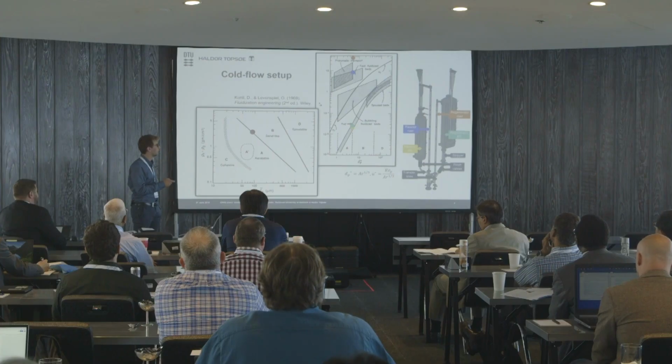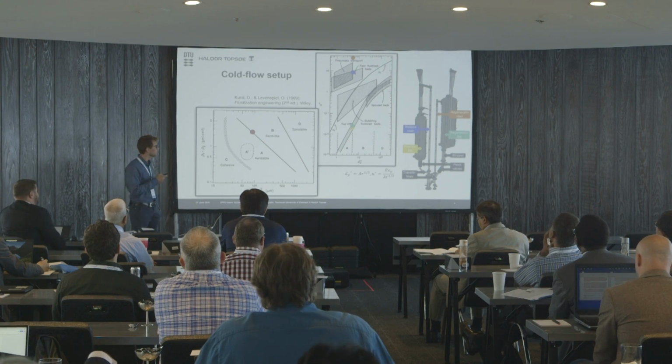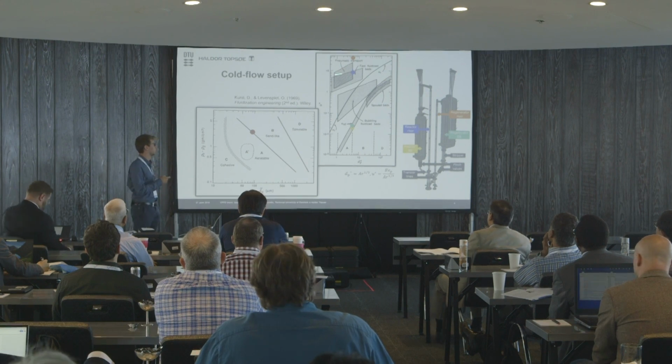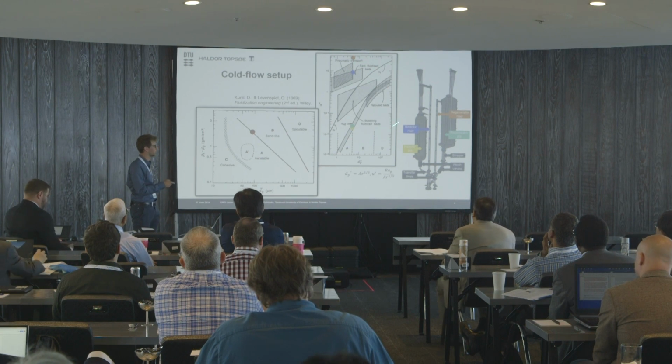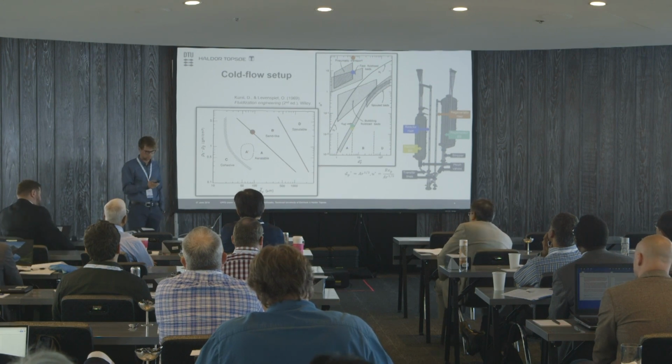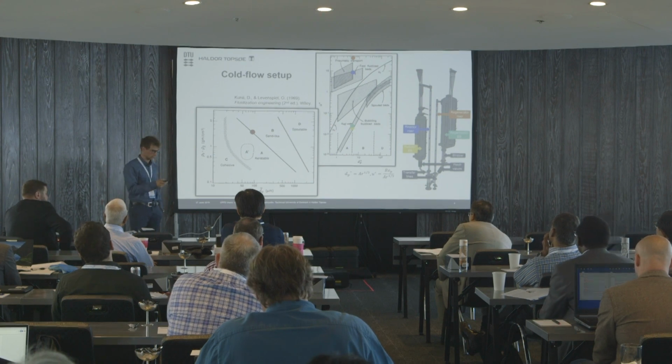And the two risers are operating in sort of a fast fluidization mode, although the superficial gas velocity in the regenerator riser is somewhat higher, so actually somewhat in some sort of transport regime. But it's not really clear-cut, these lines, but it's just to give you an idea about what we're actually trying to capture, which I think is important when you want to do CFD modeling of such a system.